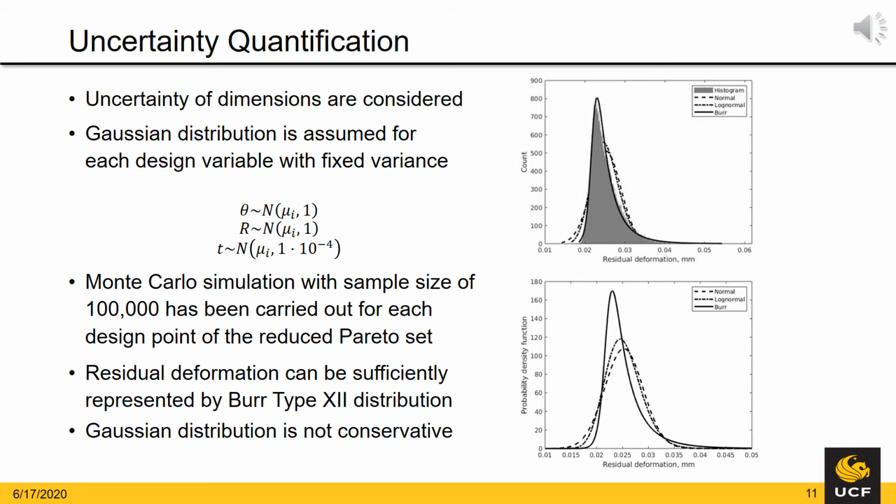After obtaining the variation, several attempts were made to fit a distribution to the output histogram. Fitting a distribution helps to predict values at locations where output points are scarce, such as long-tail regions of the histogram. The Burr distribution was capable of capturing the output histogram best, compared to a normal or log-normal distribution. It should be pointed out that choosing a normal distribution would lead to tighter confidence intervals and therefore has to be considered less conservative.